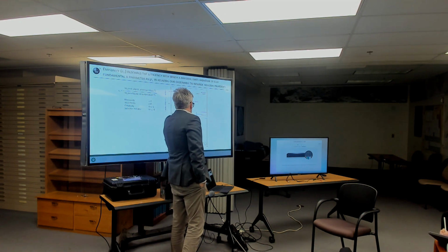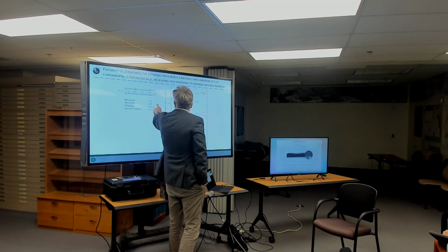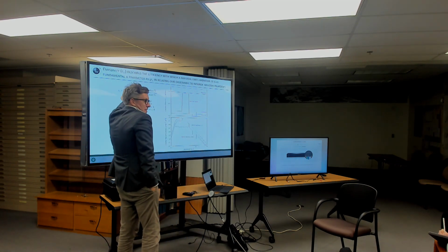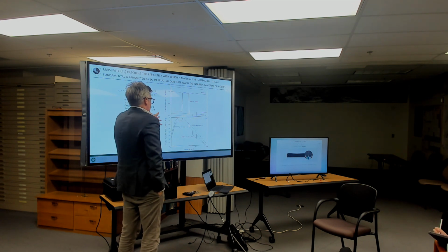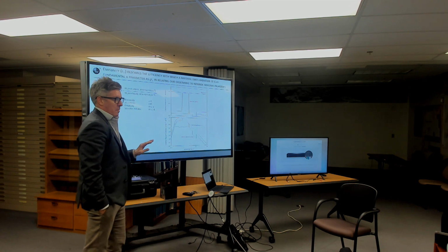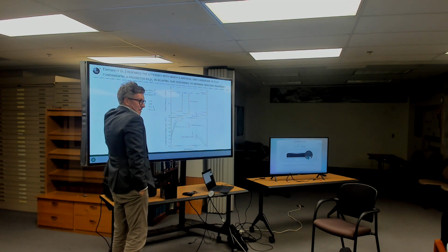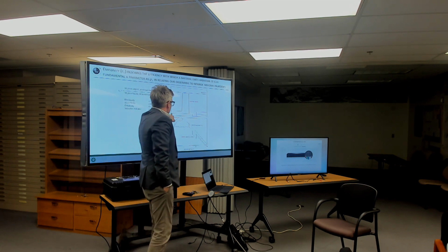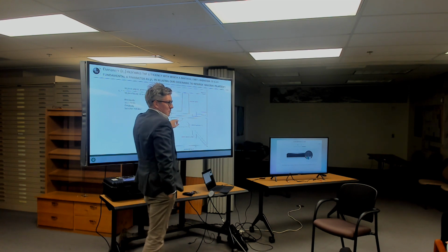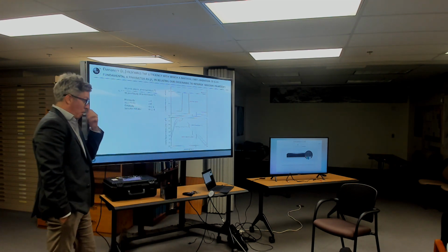So in this case, I would say, well, this is my real body at 6000 Kelvin. So at any wavelength, I would put this value in the numerator of this equation, right? And I would then say, okay, it's at 6000 K. How much would a black body radiate at 6000 K? And I would put that in the denominator. And then I would divide one by the other. And I would get this curve here, the grey body curve, which would tell me the emissivity of that grey body was 0.1, which is about 10%.